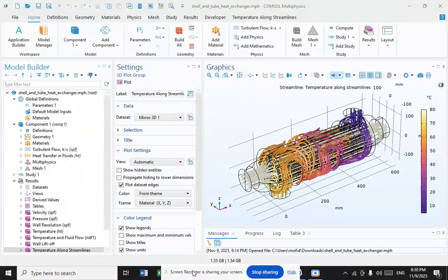confined, and etc. Shell and tube heat exchangers are typically used for high pressure applications with pressures greater than 30 bar and temperatures greater than 260 degrees centigrade. This is because the shell and tube heat exchangers are robust due to their shape. Several thermal design features must be considered when designing the tubes in the shell and tube heat exchangers. There can be many variations on the shell and tube design.